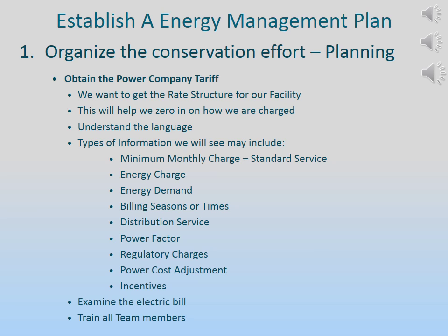Some systems have a tiered system where customers pay so much for the first thousands of kilowatts, then after that pay so much for the next group of kilowatts. This tariff does not have a tiered structure. If the utility has a tiered structure, the thing to remember if we are shaving off energy charges is we are actually shaving them off at the top end, not typically the more expensive rate. We are shaving charges off at the rate that is probably cheaper.